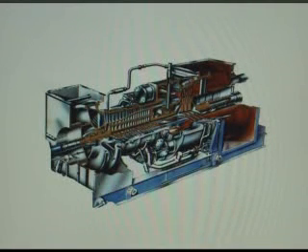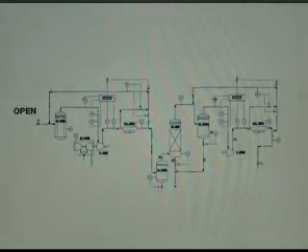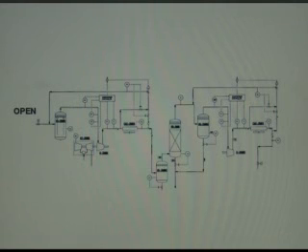The other operators who are in the area suddenly become aware that he's in great distress, but there's not much they can do because the control panel for the turbine has been isolated and shut down, so they have no control over that valve. And the way that they finally ended up stopping everything was to actually go out to this valve and disconnect the air source to the actuator so that its spring would return it to its fail-safe position, which was closed. And I think they ended up taking that instrument air connection off with a hammer.